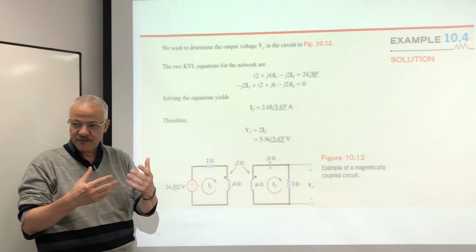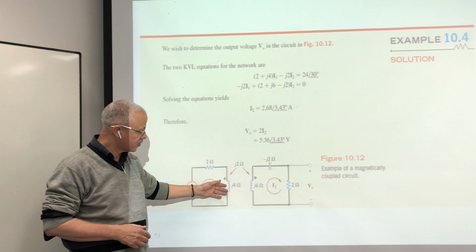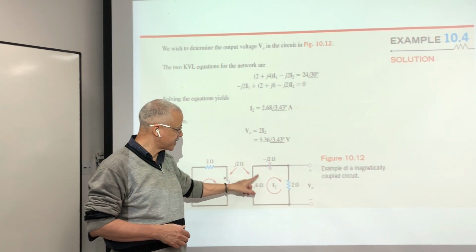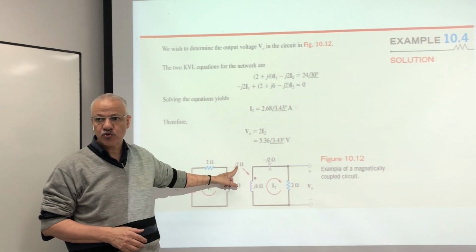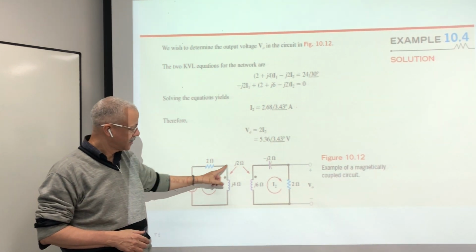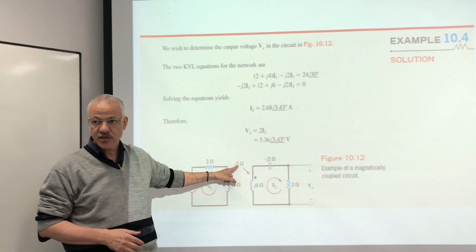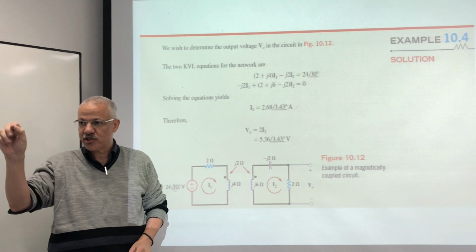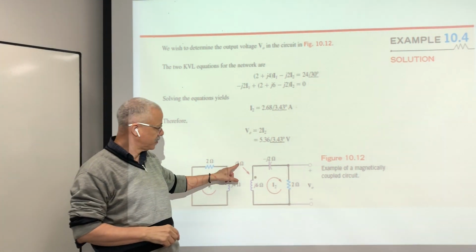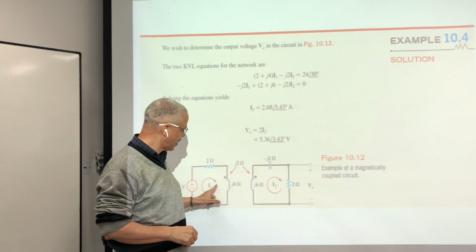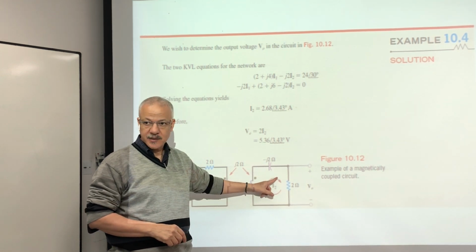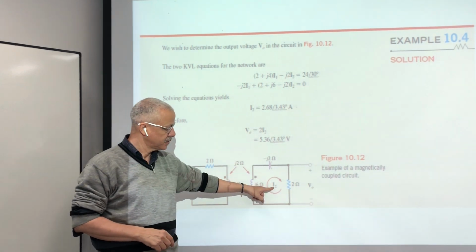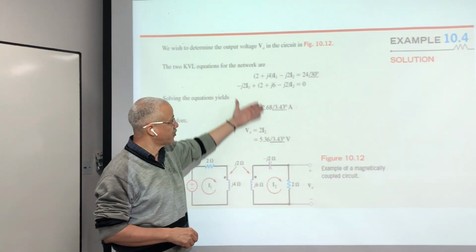So same concept. If the current flows from here, so this is entering, so it will be positive, negative, and you can add in such a case j2 I1. Now the mutual is j2. It is the mutual, like inductance in here. So you can put jM. So j2, the voltage here j2 I1. So this current leaves, so here negative, positive. j2 I2. So you can derive the two equations. It's very simple.